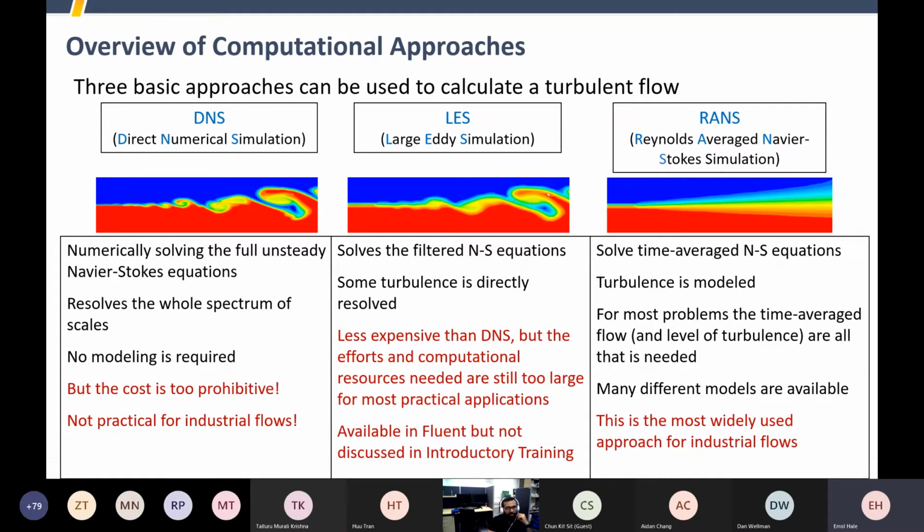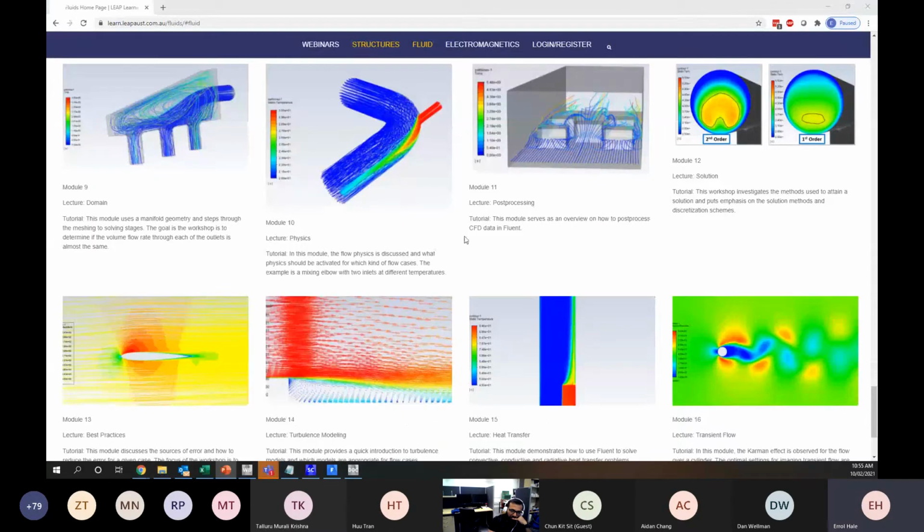Okay, so the whole point of an LES model is you need to understand where the most energy is going, into what size turbulent structures. Near the walls, the most turbulent energy in the flow is going into really small turbulent structures. So having a stress blended eddy simulation allows us to use RANS at the walls and LES in the bulk flow field. And I'll show you how to set that up and the reason we would use that.